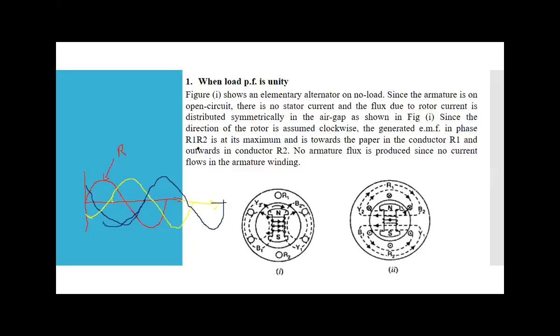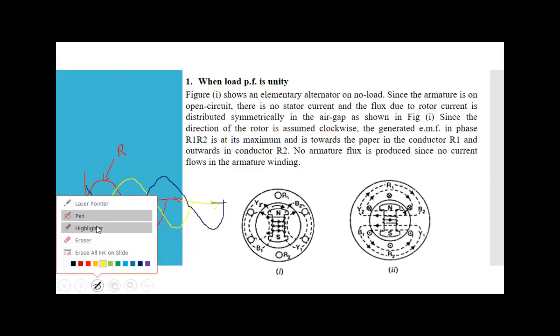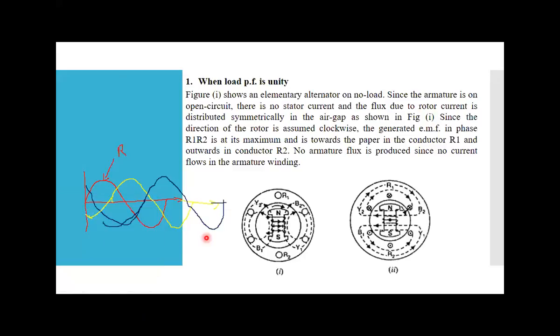Suppose you have any lab which you learned in the computer lab, and if you are using MATLAB, then simply try this. Give the three-phase supply to a purely resistive load, check the voltage and current, then give it to an inductive load, check voltage and current, and then give it to a capacitive load and check voltage and current. Then you can easily become aware of what kind of difference there is.